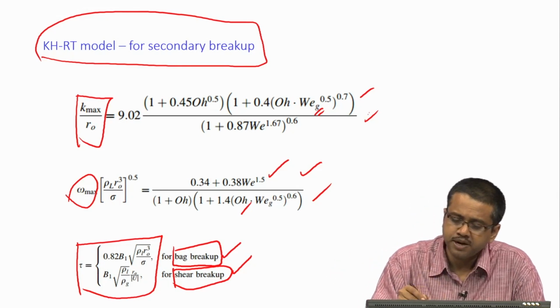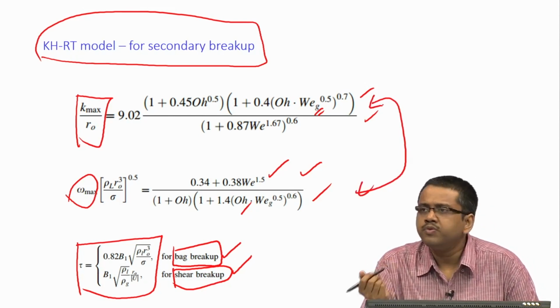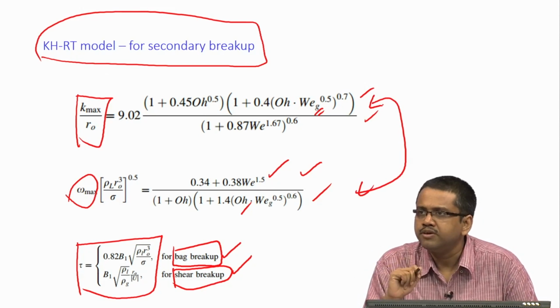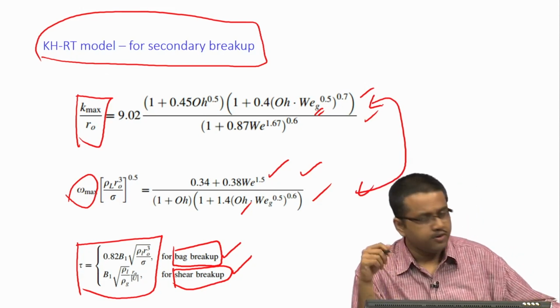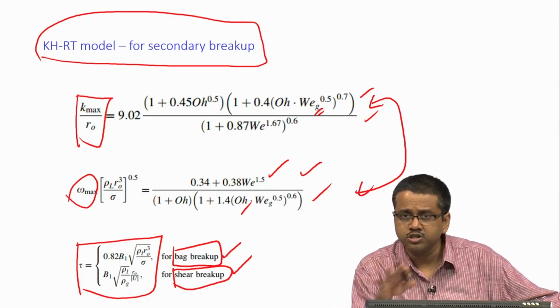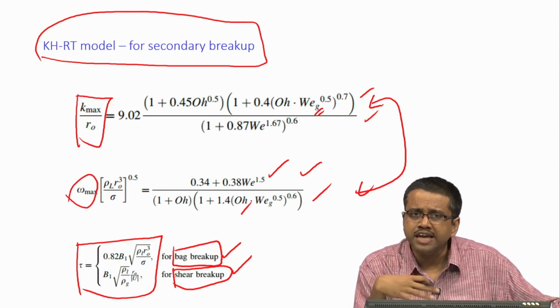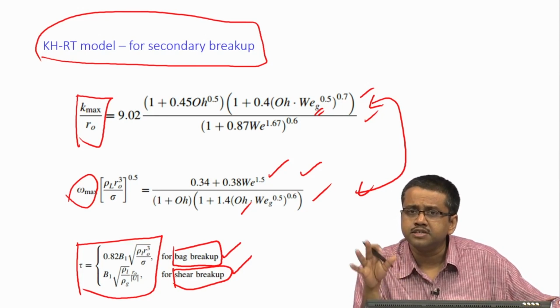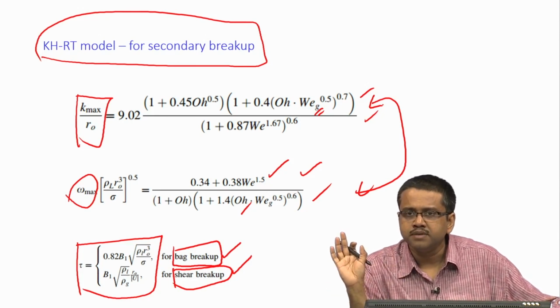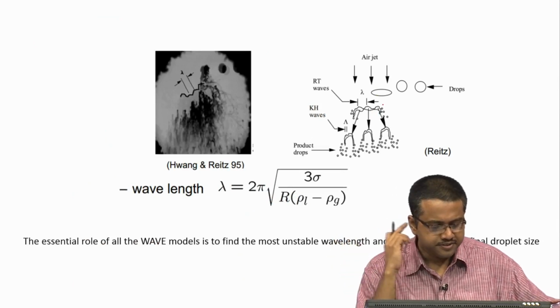in coming up with these expressions, but they are surprisingly powerful because they enable you to calculate, right, for example, the droplet diameter or the time scale, back of the envelope calculations you can quickly do, okay. For your real life situations you might have to do more sophisticated simulations, okay. These are not sophisticated, these are pure linear stability analysis, okay. So, these are workarounds, right, because ideally if you want to really predict the droplet breakup and other things computationally, you need to do something like volume of fluid or level set kind of things, okay.